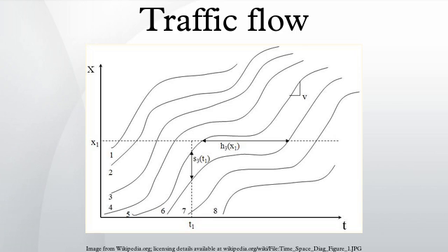Using a one-lane signalized approach to an intersection as an example, where x1 is the location of the stop bar at the approach and x2 is an arbitrary line on the receiving lane just across the intersection, when the traffic signal is green, vehicles can travel through both points with no delay, and the time it takes to travel that distance is equal to the free-flow travel time. Graphically, this is shown as the two separate curves in Figure 8.